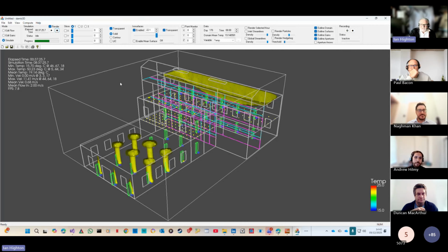Yeah, and I need to fill that one in because lots of people say that, the time step is 1 hour. No, it's a Laplace transform solution of the Fourier heat conduction equation, which means it's analytical, which means our time step is effectively infinitesimal. We happen to report hourly because that's just the way the weather data works. And all we get is weather data for the previous hour average. So in all honesty, there's not a lot of point us reporting any more accurately. There's nothing to stop us reporting continuously.